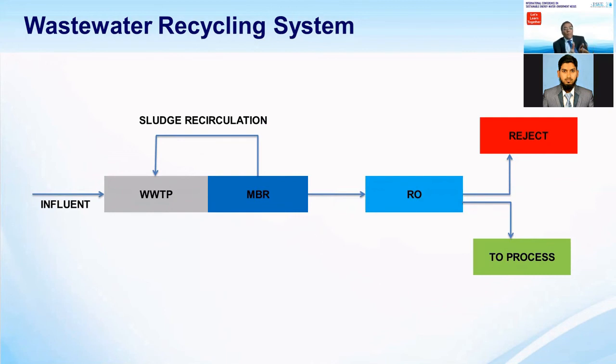You have a modified wastewater treatment plant based on the activated sludge process, and instead of a secondary clarifier, you can put an MBR. It's not strictly exact, but for your understanding, I'm just explaining. These are also membranes, and this membrane gives you much higher return sludge. In a conventional system, in the aeration tank, you can maintain the MLSS up to 4,000, maximum 5,000. And MBR membranes are of two types.